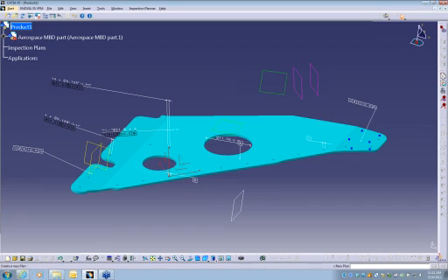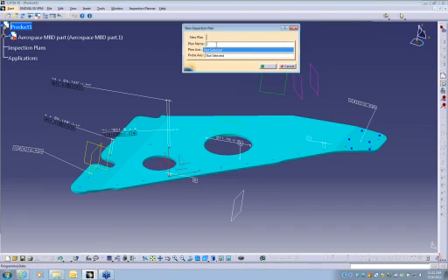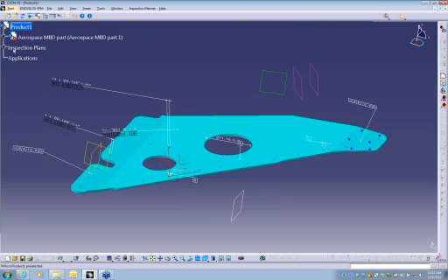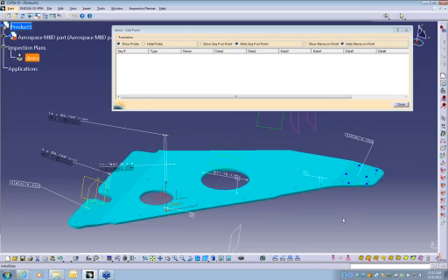We start a plan by hitting this icon, and we'll just call this demo. First thing it's prompting us to do is pick where we want our datum from. We're going to pick this local datum axis, and then it wants to know how we're going to align our probe to the part. The next pick is kind of how your part is orientated on your CMM. So we'll pick that axis, and we'll say OK. And we started our plan.